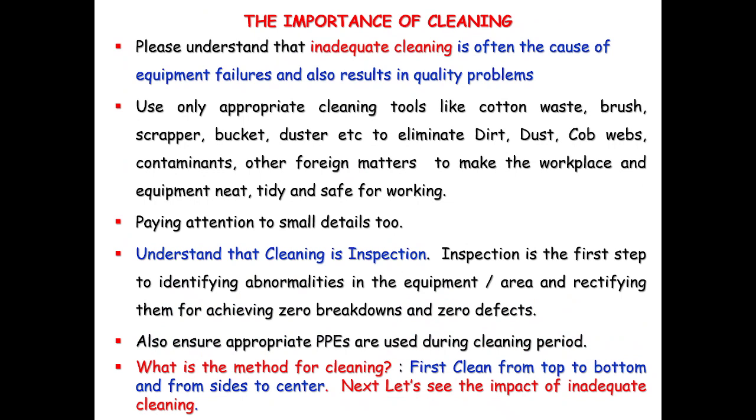This slide highlights the importance of cleaning. Please understand that inadequate cleaning is often the cause of equipment failures and also leads to quality problems. Use appropriate cleaning tools like cotton waste, brush, scraper, bucket, duster, etc. to eliminate dirt, dust, cobwebs, contaminants, other foreign matters to make the workplace and equipment neat, tidy, and safe for working. Also ensure appropriate PPEs are used during cleaning period to ensure safety.